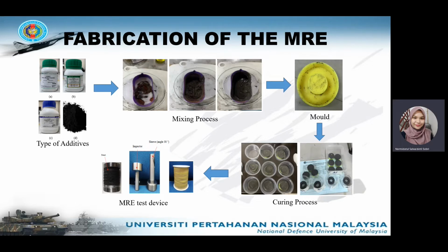The fabrication starts with the mixing process. All the components will be mixed manually in a container, and the mixture will be poured into a mold. After that, it will be cured for about 24 hours, and the cured MRE will be put into the MRE test device for the impact testing.